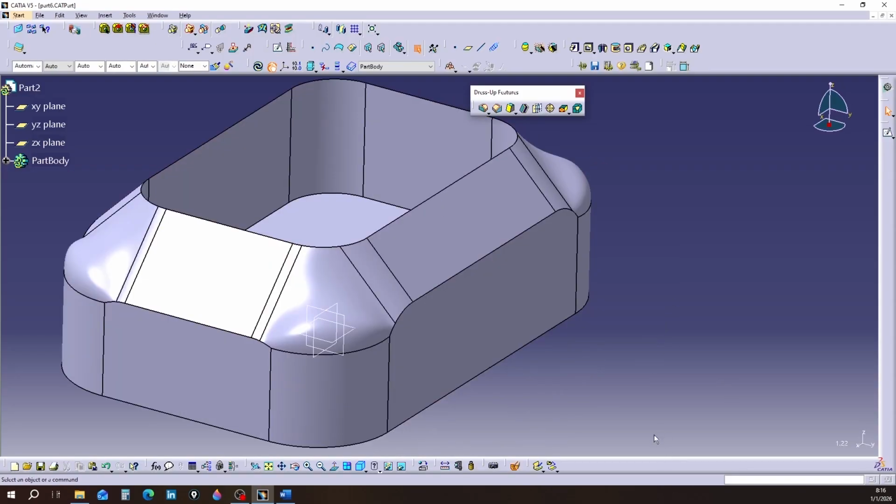Important points to keep in mind about whole curve. This mode is excellent for connecting several surfaces, variable chamfers, and mold parts. The models you saw were all related to using internal curves. My advice as your teacher: always check the orange arrow first. This avoids mistakes on the reference face. Chamfering is not just for beauty. It removes dangerous burrs. It also makes part assembly much easier.